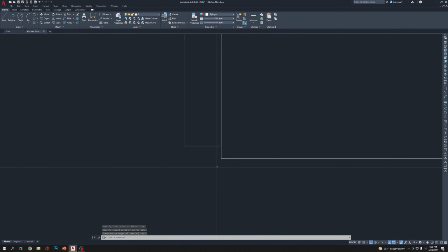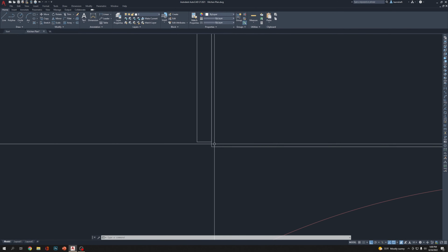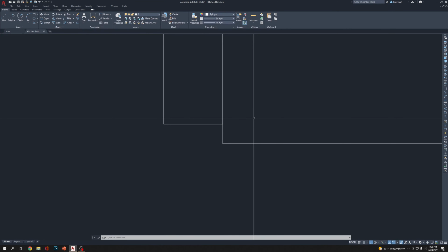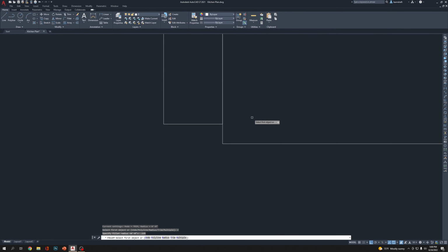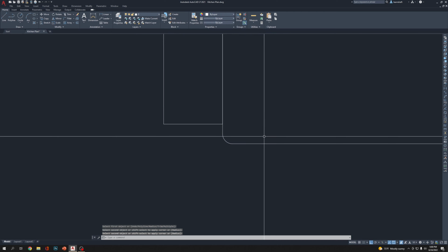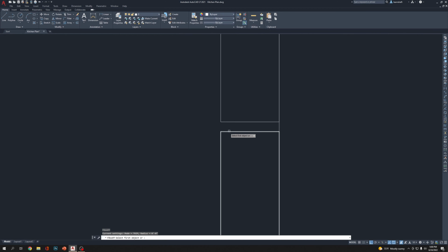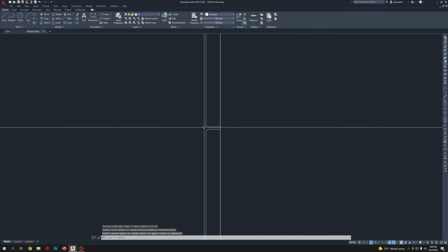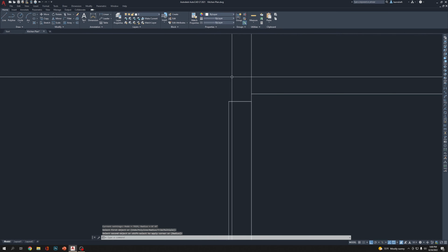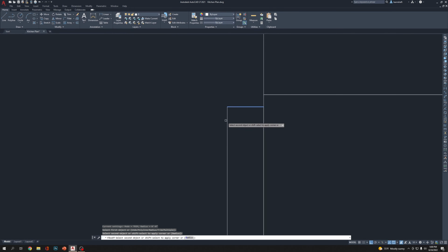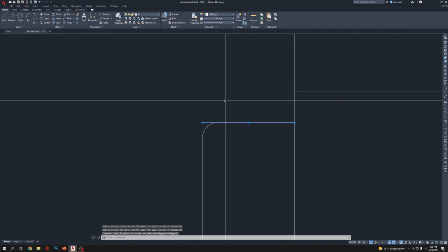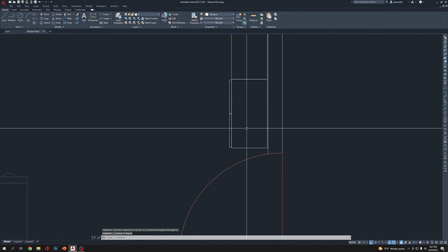So we should have this corner a little bit, instead of sharp corner, gonna be a little bit round. So gonna be fillet, F, enter, radius, enter, 0.125. Let's see how it looks like. Yeah, 0.125 is good. Yes, enter. So they're not gonna hurt anybody's hand, head, or anything. This is the first line we draw, remember? So I have deleted it.